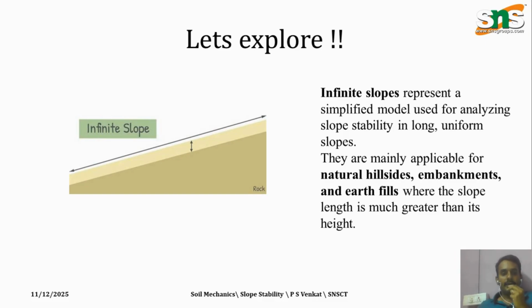So you will find infinite slopes in natural hillsides, embankments and earthen fills. The assumption is that the soil properties, slope geometry and loading conditions remain constant over a large extent, hence it is treated as infinite. This helps engineers to analyze slope stability in a manageable analytical way without involving complex geometry.